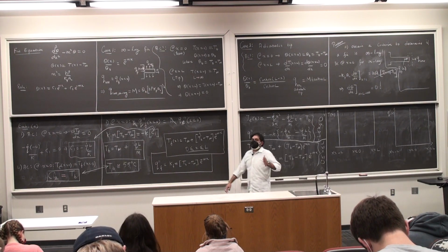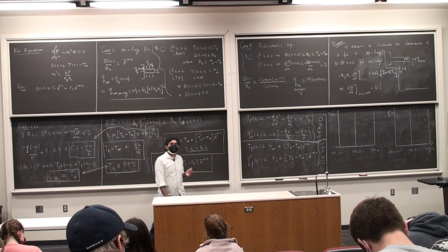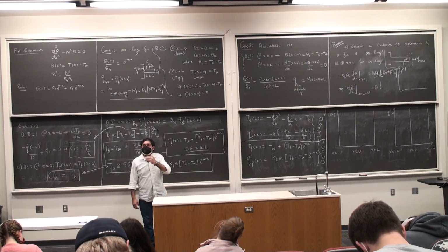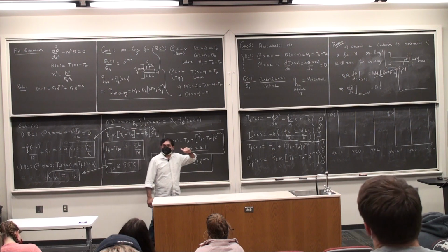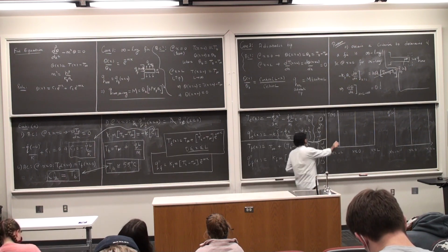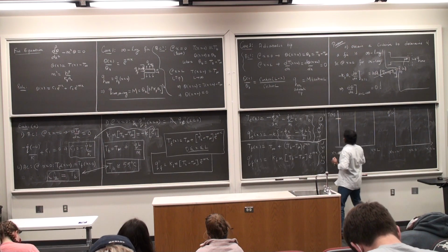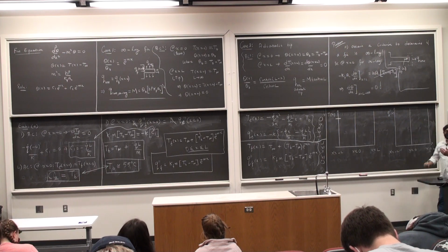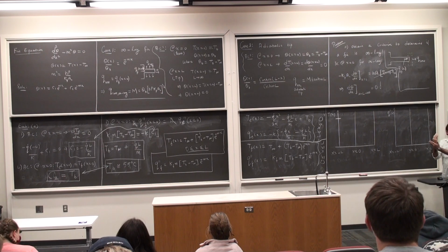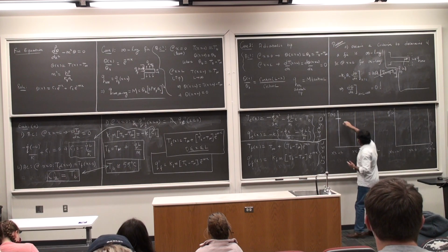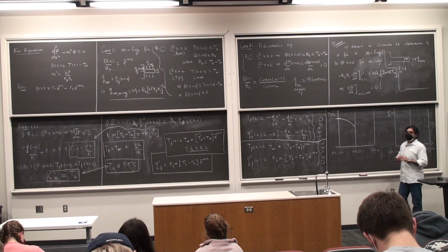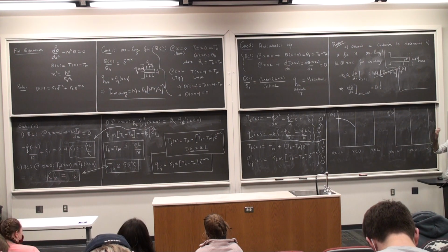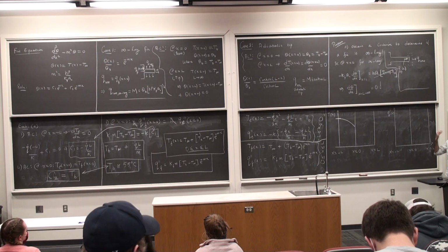If you want, you can calculate the temperature at the end x equal to minus L. You will end up having a much higher value because there is heat generation taking place. So I start off as adiabatic, so 0 slope. And then we know that the direction of heat transfer is going to go from x equal to minus L all the way to x equal to L. And so the profile has to follow the following curvature. This signifies that the direction of heat transfer is along the positive x direction.